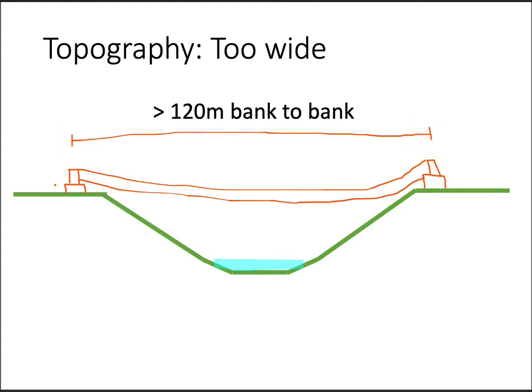And so why is this an issue? Okay, well, one problem is that it's very long. You have a lot of tension in the cables. You're going to have to build really massive abutments in order to withstand this force. So that's one thing. It just becomes a lot of rock, a lot of material that you're going to have to build by hand. It's a lot of masonry. But another thing is that you have this surface area of the bridge here. And so you can see, obviously, as the bridge is longer, the surface area increases.